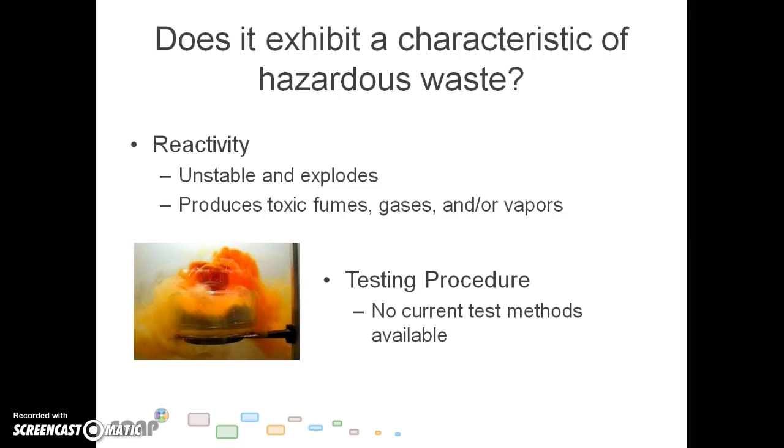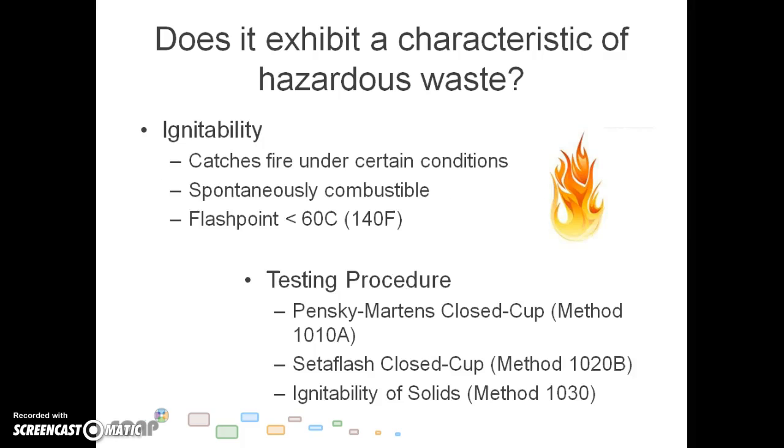A waste is considered reactive if it is unstable, explodes, or produces toxic fumes, gases, and vapors when mixed with water or under conditions such as heat and pressure. Examples include waste from cyanide plating, sulfide-bearing waste, and oxidizers. There are currently no test methods available for reactivity.